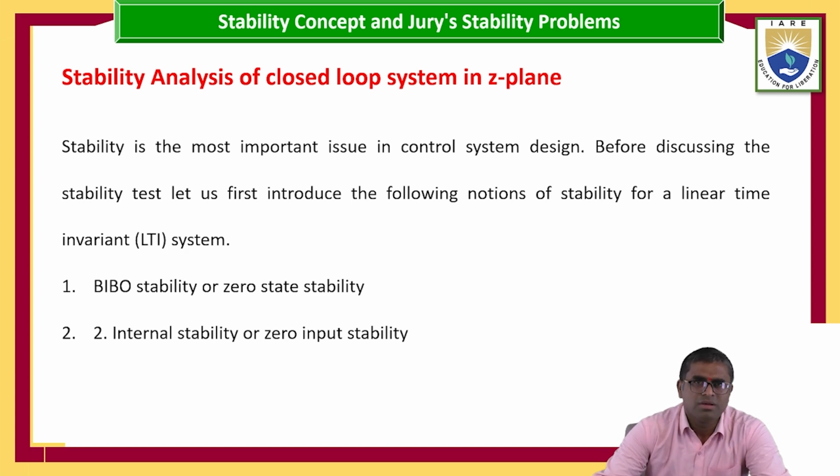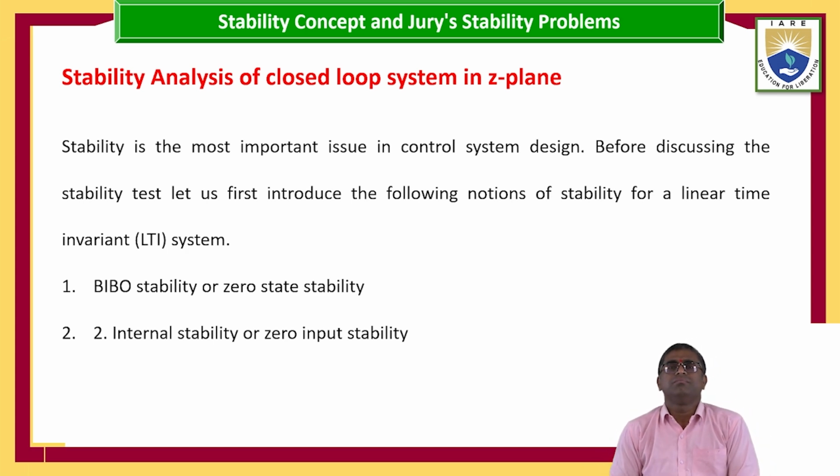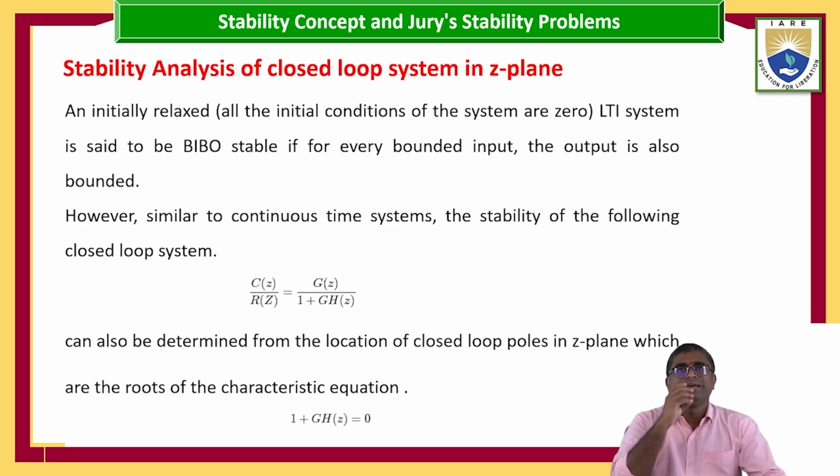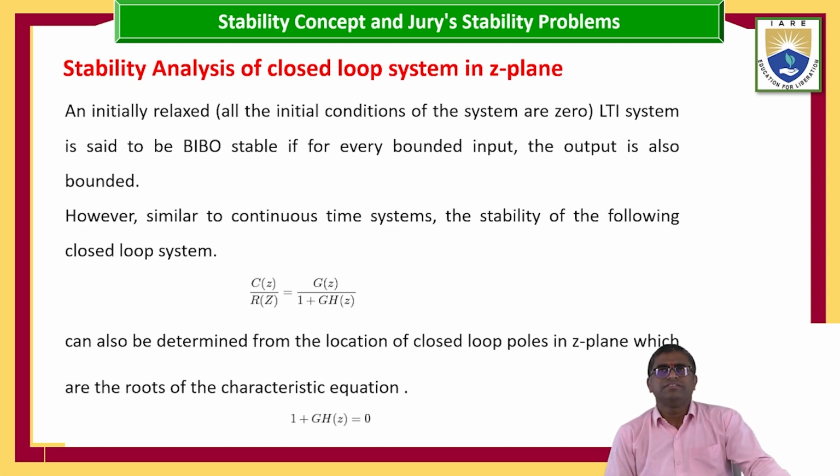That is, BIBO stability or zero state stability. The second one is internal stability or zero input stability. Initially, we say that a linear time invariant system is said to be BIBO stable if, for a bounded input, the output will also be bounded.